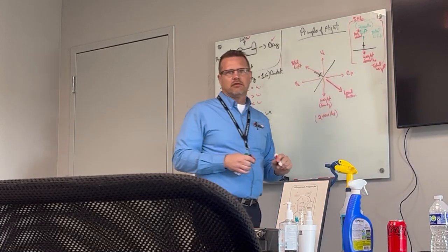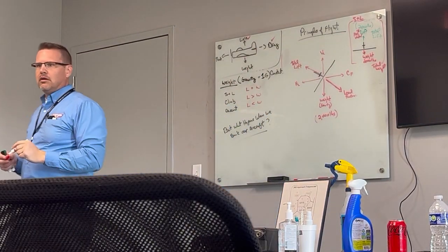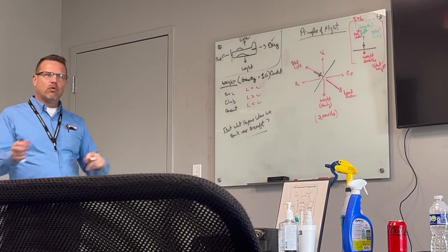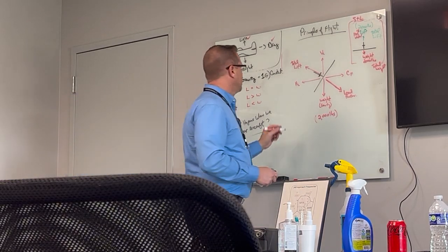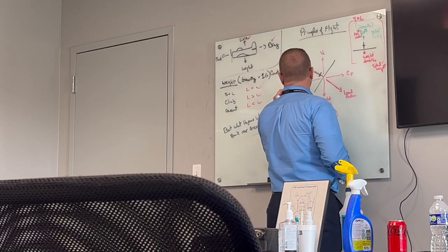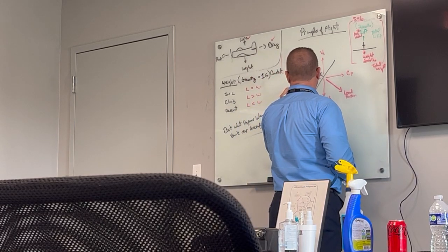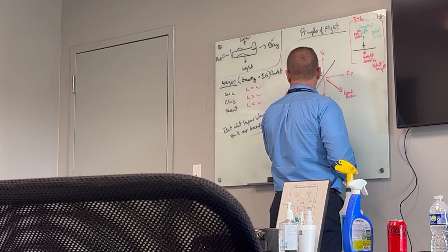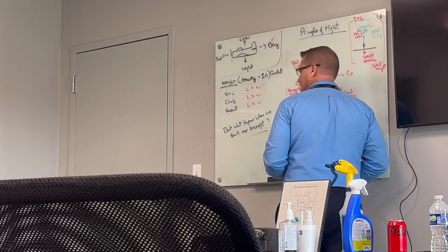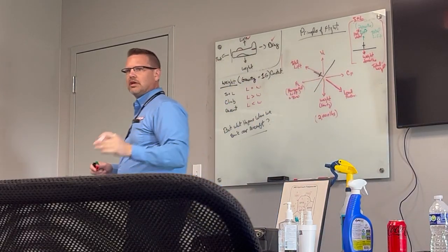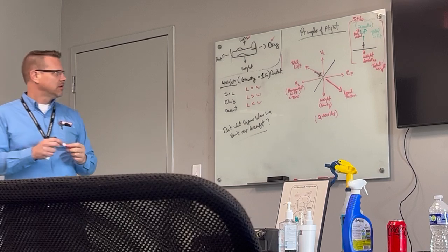It's all vertical lift. We have to trade and give away some of our vertical lift and trade it for horizontal lift. And this is so we can actually turn the aircraft while we're banked, okay?